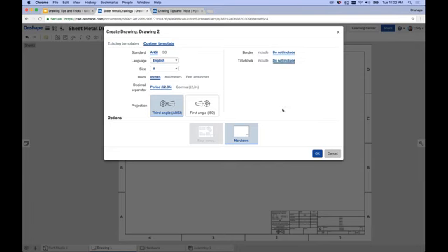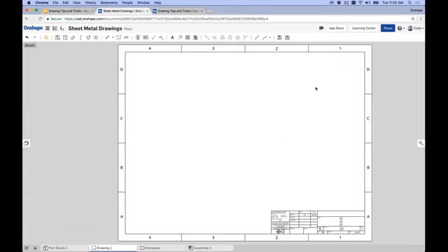If you do this, you can insert your own DXF over the top of a blank drawing sheet and save that as a template. Make sure to set your line thickness, insert your linked properties, those kinds of things. But that's how I would take a SolidWorks drawing template, save it as DXF, and use it to build my own template in Onshape.